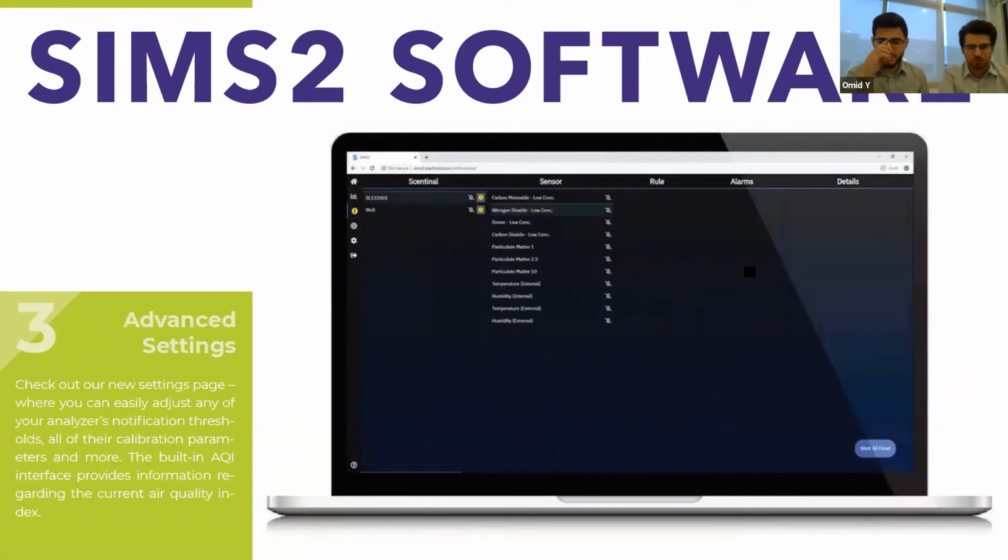And in the same place, you have some advanced settings that you can play around with. You can set the calibration parameters and the AQI values, the indexes, and all of that here. You can also adjust and select here. You'll also be able to set up your alarms here for SMS messages once a sensor has reached a threshold that you've set. Those are per sensor, so you can configure different levels for each sensor as you would like.